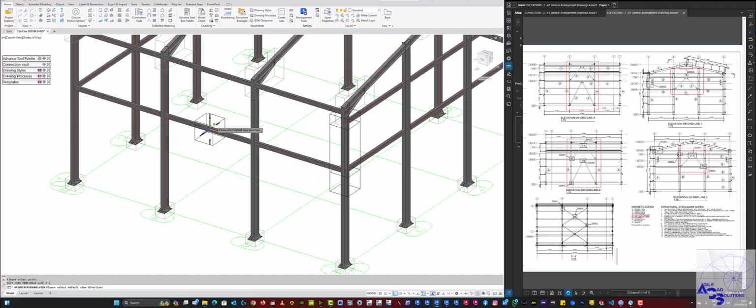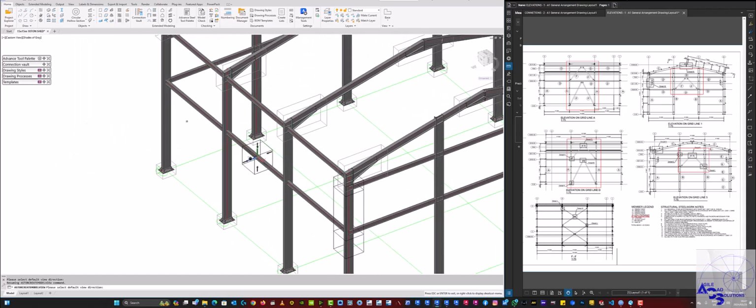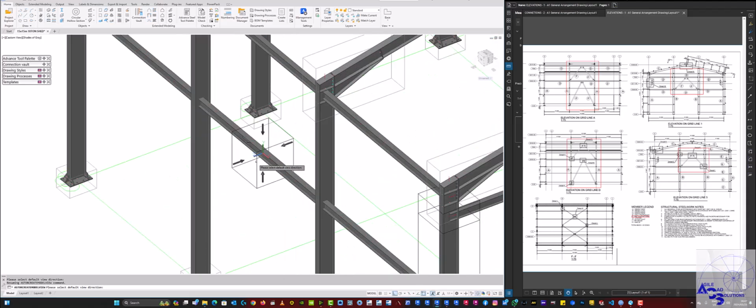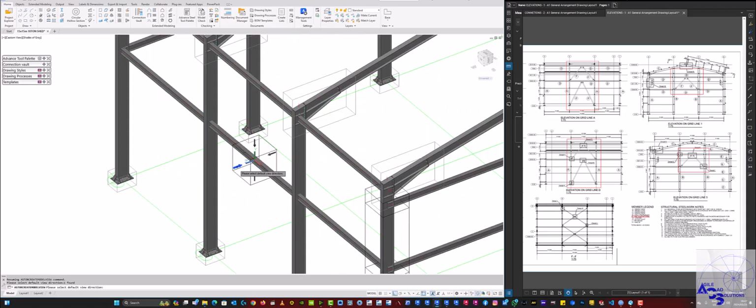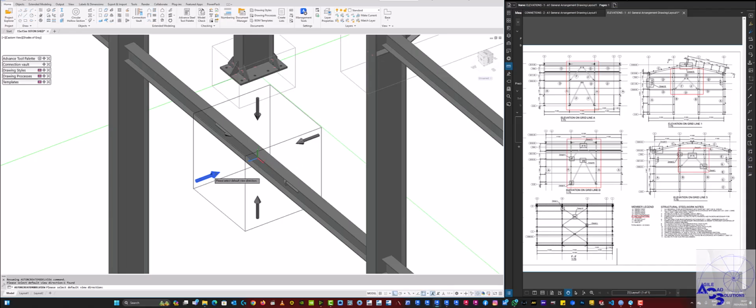All right. Now you have to select the view direction. You want to view it from the negative side of Z or the positive side, or whichever direction. So in this case, you want to have a view from the positive side. That means from outside to the inside of the frame. So we're going to select that arrow there, not the UCS, but these arrows. That's what you select. So we have selected the arrow along the Z. So let's say enter. So now we have finished setting it up.